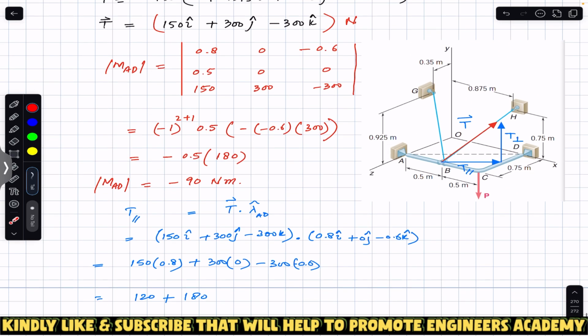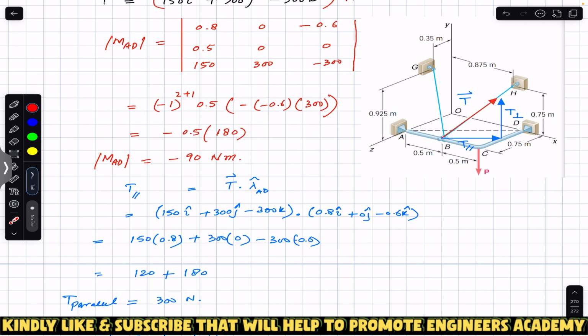Now, as you can see, this tension T is going to produce a moment about AD. If we resolve this tension T into two components, one along the AD line and one perpendicular to AD, the component parallel to AD is not going to produce a moment about AD.